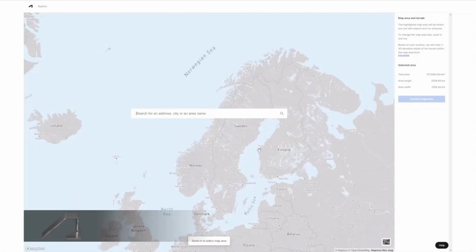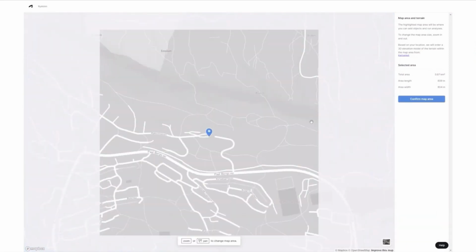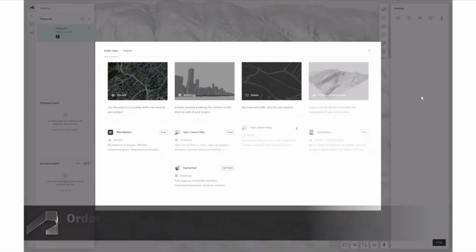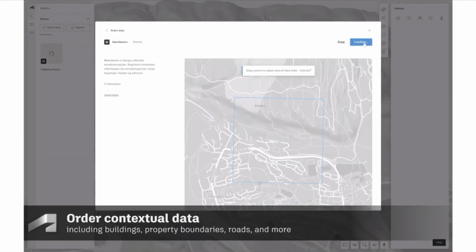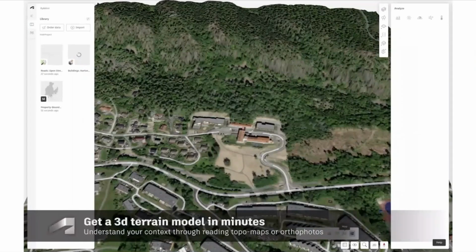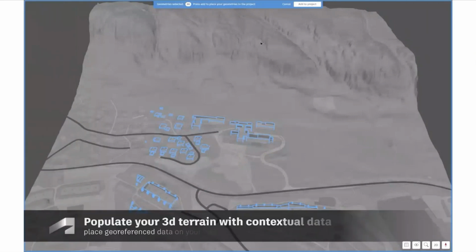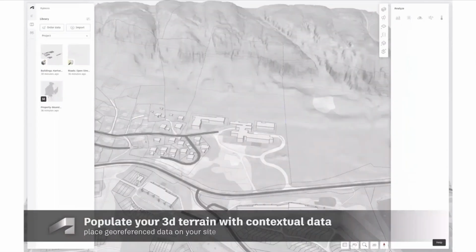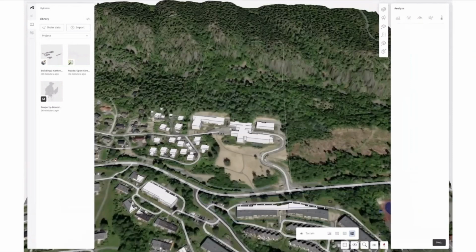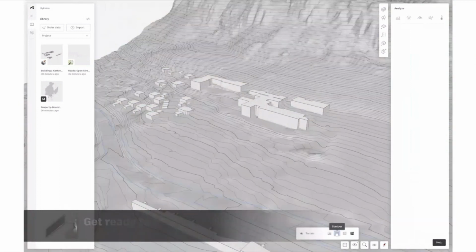So it originated out of Norway, hence why we're starting with a Scandinavian site here. So this is how you create your site model. You choose the part of the world you want from the address, and then depending on where it is, the data will be made available. If it's not got local providers, then OpenStreetMaps will be the default. It will bring down your site terrain, the local building information, building data, and aerial imagery. Site boundaries are available, roads and rail information as well. Now, if you don't have this information available, you can still import it in as an OBJ or IFC file.